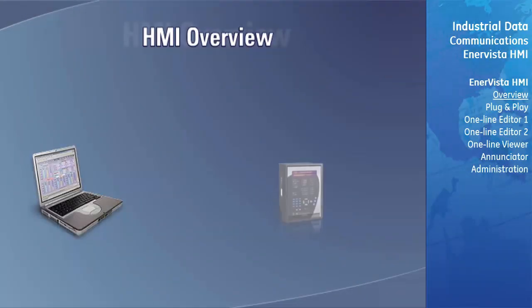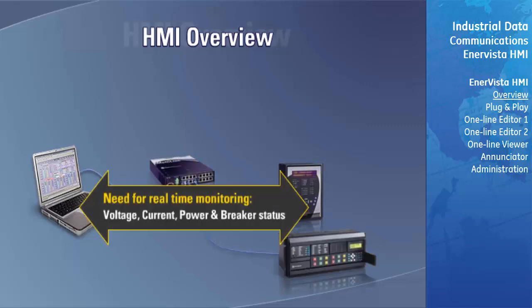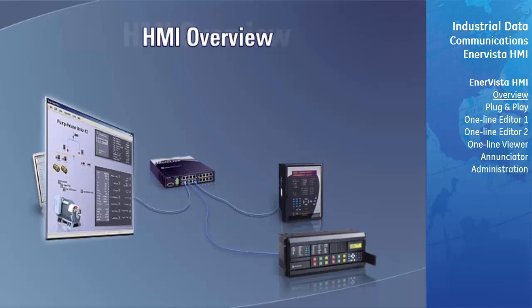Often, there is a need for real-time monitoring of protective relays and their power system quantities, such as voltage, current, power, and breaker status. There is also frequently a need to perform control functions, such as manually opening and closing a breaker. The system that performs such functions usually takes the form of a single or multiple computers running a special software package. The resulting system is referred to as a Human-Machine Interface, or HMI.